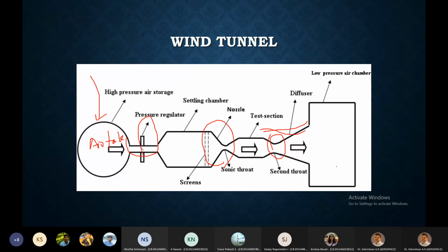Now, when we talk about liquefaction, what we are saying is that the air in this section should not come to be below the liquefaction temperature. And when we ask whether it requires preheating, what we mean is whether, either in the tank or in the settling chamber, we need to heat the air. That's the context of the question. Now let's go back to the problem.